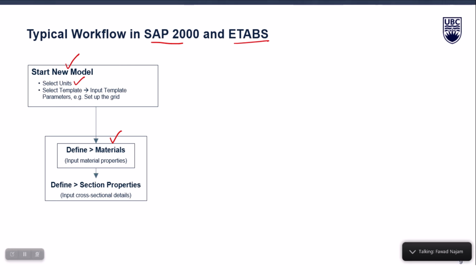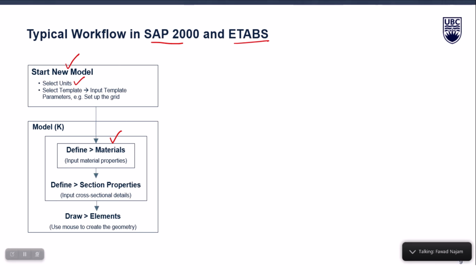Third step will be that once you have all the cross sections which your members are made of, then you can start drawing your structure. You can have grid lines on a canvas which can guide you how to draw your structure. So, actually you are giving lengths and connectivity and angles, all that information to the program, right. This will complete the process to determine the K matrix by the program, right. Depending upon structural complexity, it can be, as I said, a 50,000 by 50,000 order matrix, right.